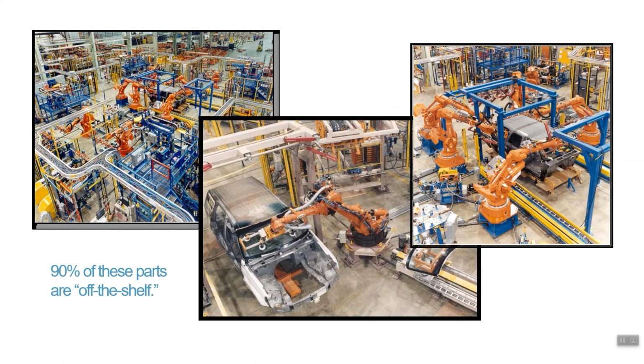So when it comes to thinking in standard parts, especially when it comes to something like brackets, the point is, you might not be able to have the perfect bracket that will work in every situation, but you can take a bracket and add extra mounting holes to it, or add different configurations to it that aren't useful in every single design, but make it useful in a much broader context. So the more parts that you standardize and specifically create for standardization, the more that you're able to use those parts effectively across different designs.